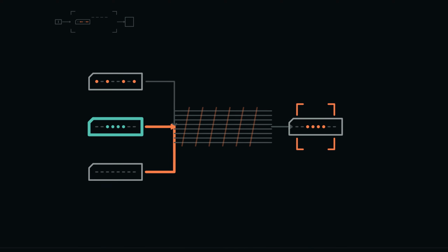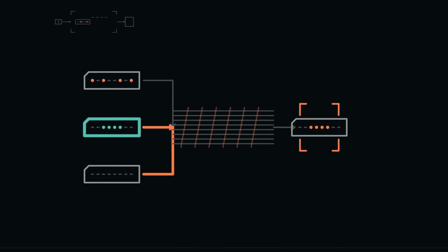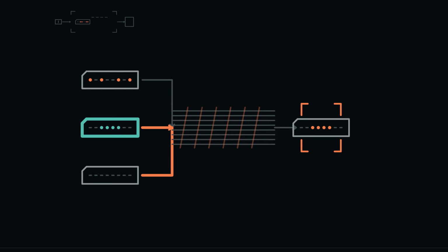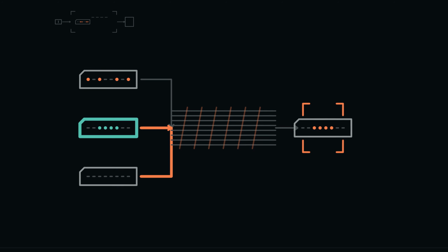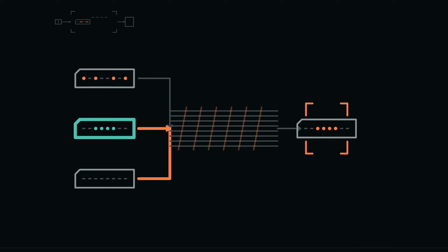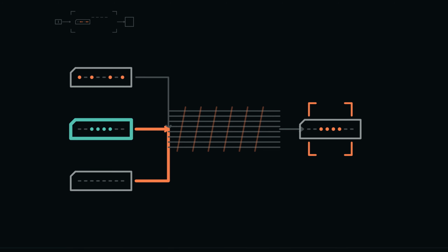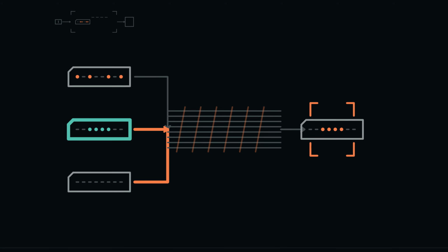Now violate the access rule. R2 tries to drive a 1 on a line, while R3 tries to drive a 0 on that same line. The result is not a useful vote, and it is not automatically either source's value. Real hardware can produce excessive current or an undefined voltage. Our architectural model labels the transfer invalid and forbids the state.